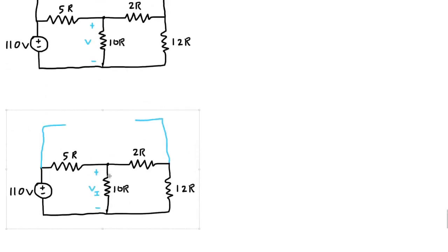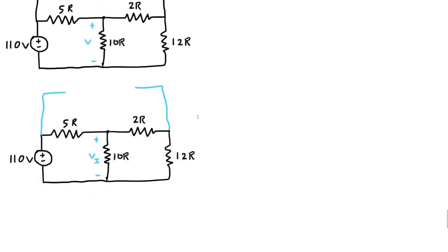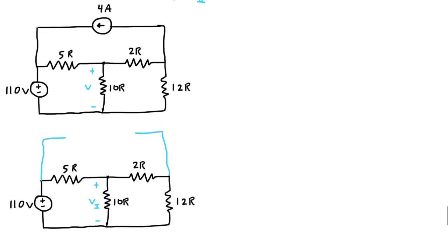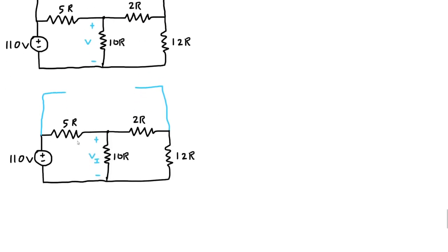So the way we're going to do that is we're going to consider each case individually. The first case is where we shut off the current source. It's high impedance, so open circuit. And then we're going to do the math and find out, hey, what's V1? So we got another circuit here. I'll call this I2, I3, and this is also I3. I should have labeled it first.